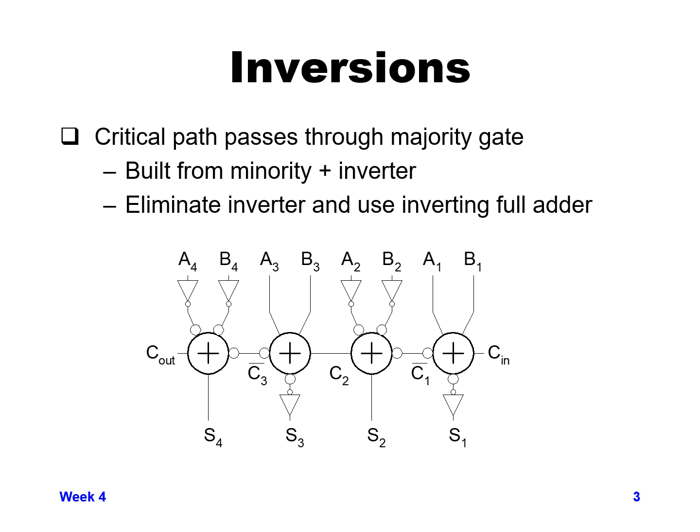If we use the same full adder for every bit, if we use an inverted version of the full adder, and we know we're implementing C out versus C out bar, we can actually remove an inverter from every stage for the carry. So this can speed us up by possibly a factor of 2, but we still have to wait for the carry to propagate through bit after bit.